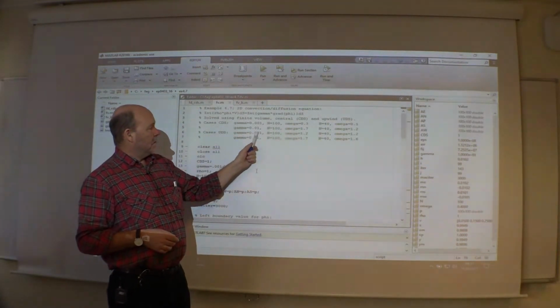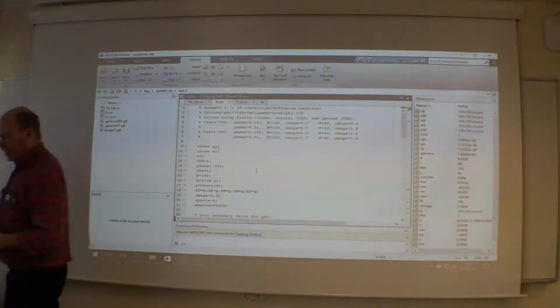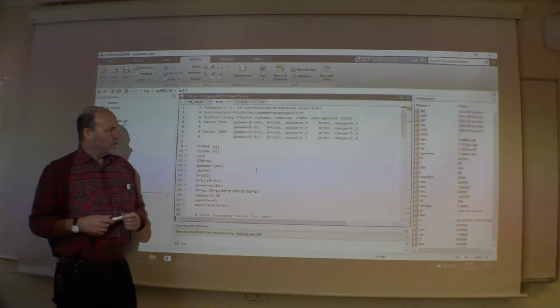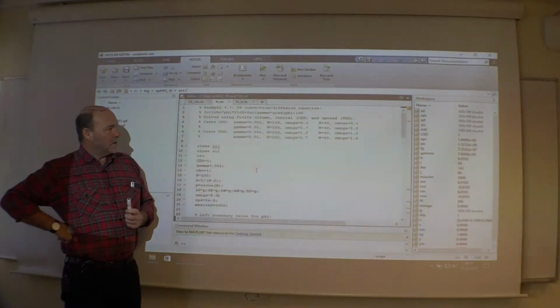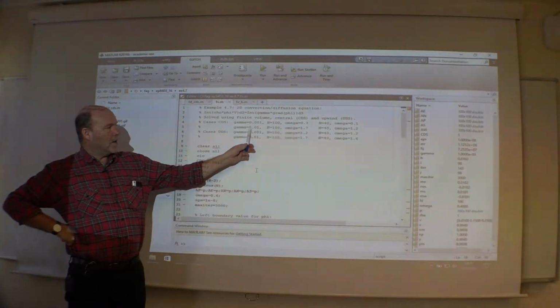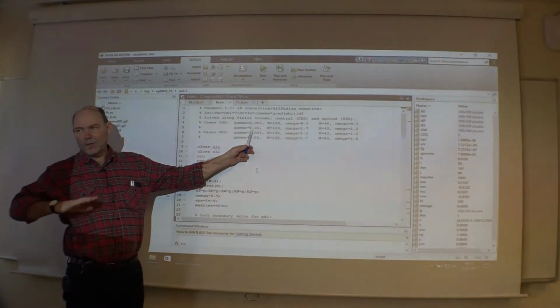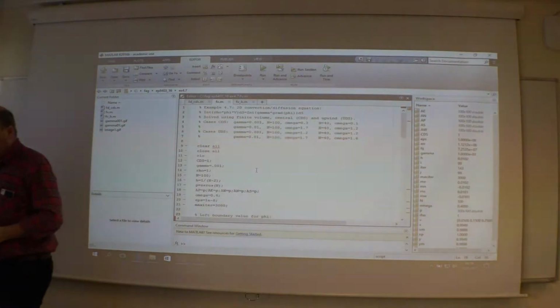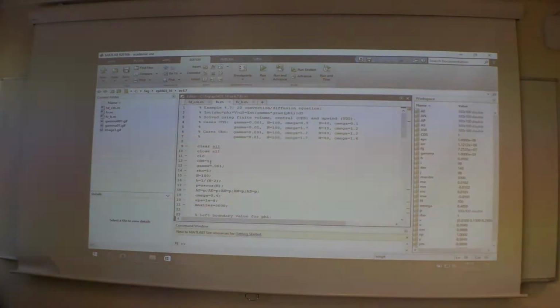Increasing the gamma sort of softens it down. Remember, you divide by this gamma, the viscosity, to create the local cell Reynolds number. So when gamma is big, then it's more and more stable, of course. So small gamma, that's the problem. With a bigger gamma, we get a solution fairly quickly. So now I can go back to the bigger omega. 1.7 should be stable.